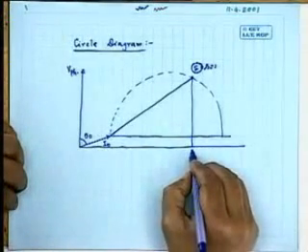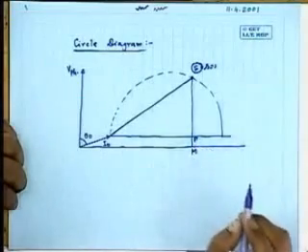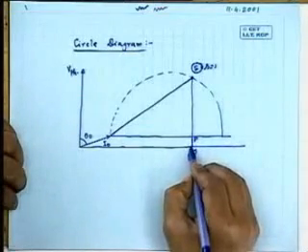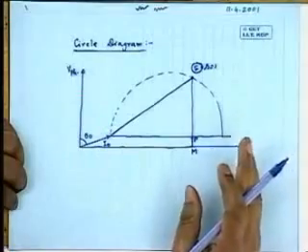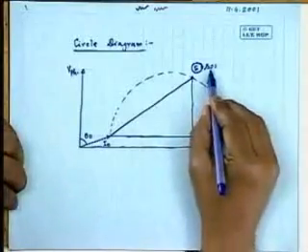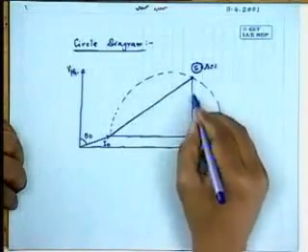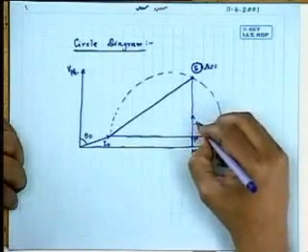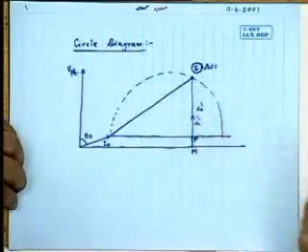So SM, say P you call, SM is the total input power to the system. From this, if you subtract the core loss, you get the remaining power which will supply the stator copper loss, rotor copper loss and output mechanical power. Now, during standstill condition, this line SP, you break it up in the ratio R1 is to R2 dashed. Suppose these values are known, in this ratio you break it up.